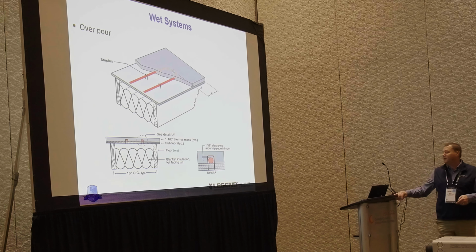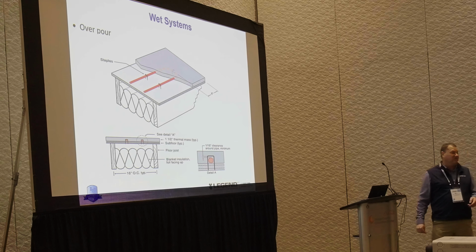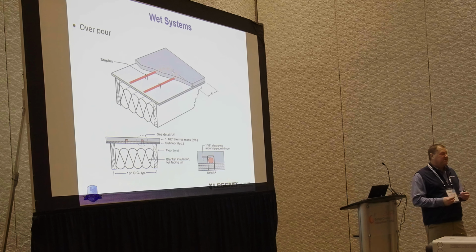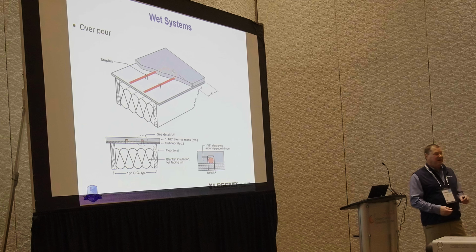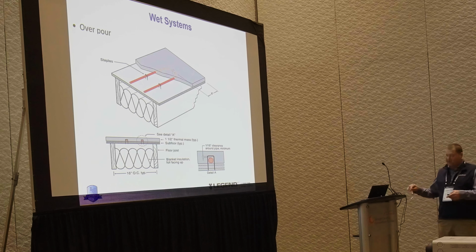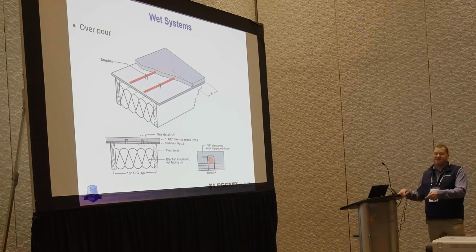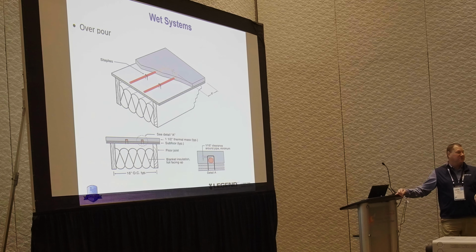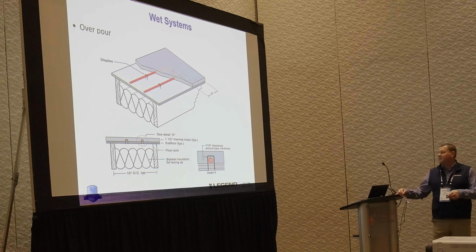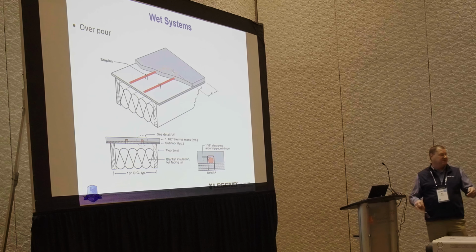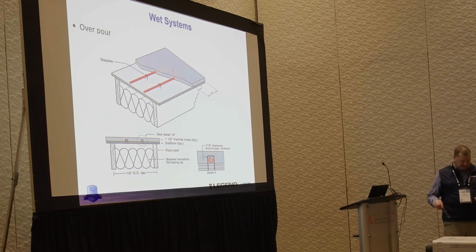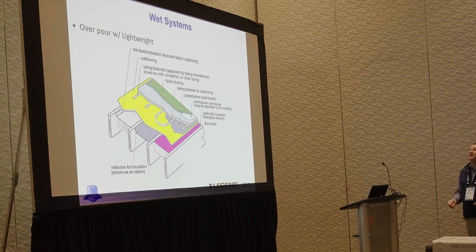If it's a residence where we can staple down the tubing, we want to make sure the staples are not crushing that tubing. If you've got an old stapler that staples into wood, those are calibrated, you can adjust them. But if the staple comes down and it pinches the tubing, it's not intended to do that. It's intended to hold the tubing in place until the cement's poured so that it doesn't move around. So making sure that there's a small gap and the tube is not pinched in there and it can move freely is a good best practice to do with that.